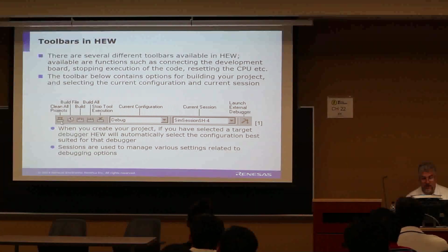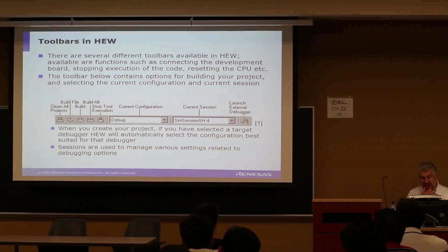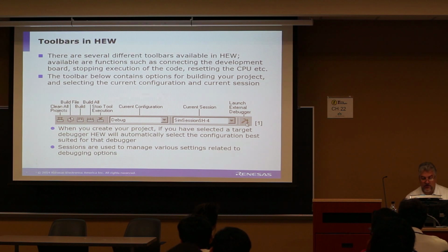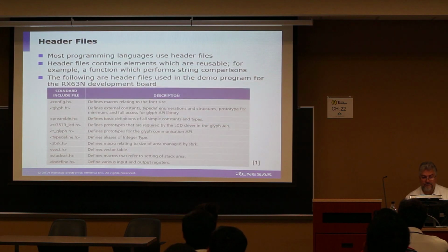Simply, you can clean all projects, you can build an individual file, you can build all the files, and then you can actually download and execute as well. Here we go. Launch external debugger is another common one that is helpful.